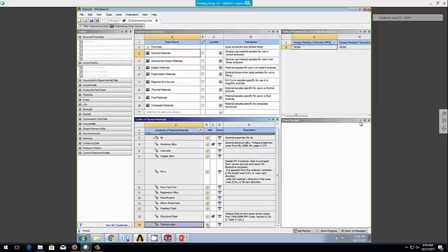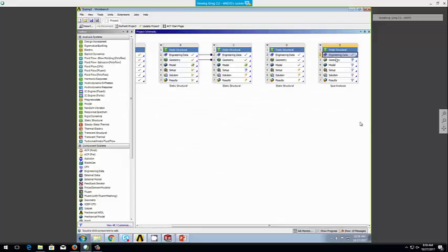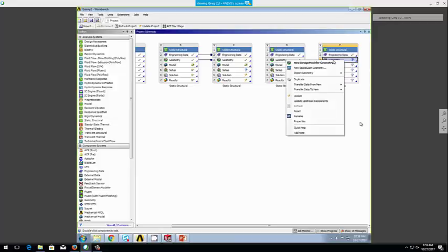What I'm going to do now is put on another load. I'm going to put on a force. I want to pick this face, apply that, okay? And I can apply that along that face. So now what I currently have is a magnitude of 0 with a vector. By creature of habit, I like to specify components. So now I can begin to specify the components here.